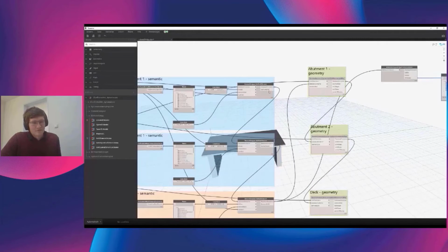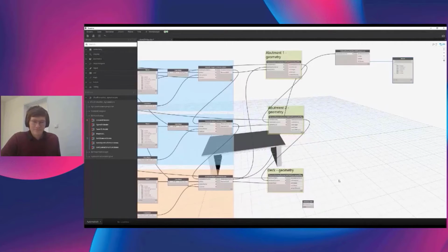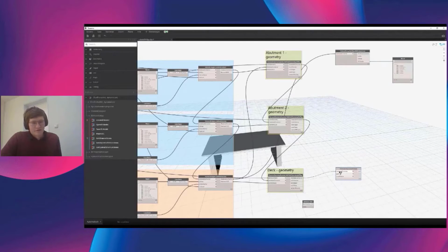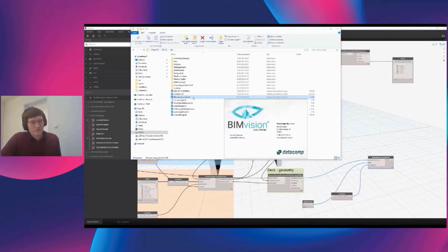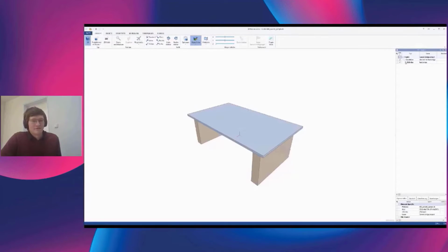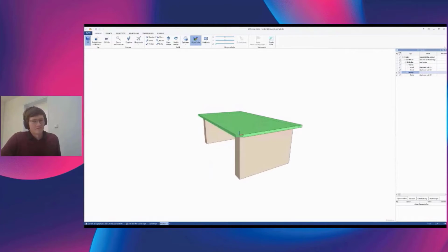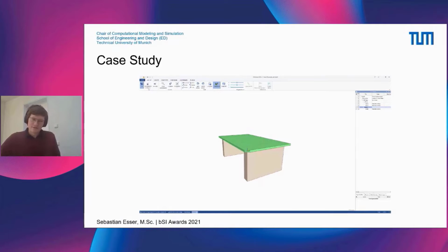And what now happens within these green boxes is basically that we assign the geometry to the semantic products of the abutments and the decks. And last but not least, we insert a node which does the model saving, so it stores the resulting IFC model we have just composed within our canvas to our disk, locally. And we can also then directly go to a BIM viewer, BIM Vision in that case, and we see the model visualized here. And we also see on the upper right, which might be a little low, these 3 components together with the geometry. So that was a really simple example.